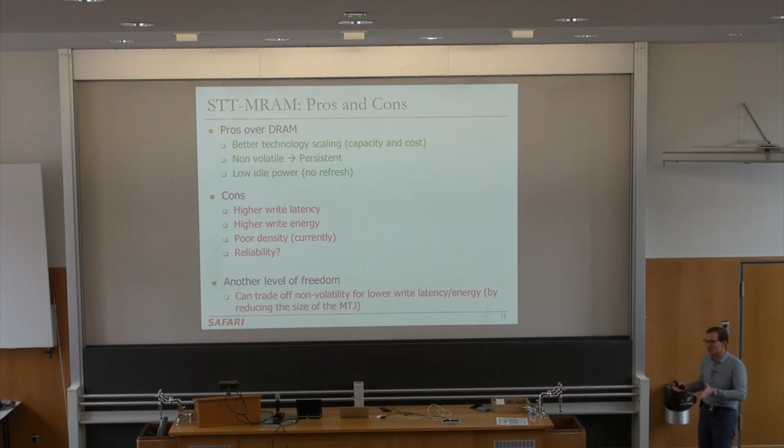Downsides also, of course, right? Persistence always also comes, if you have some data that's stored over there, now if someone else can read it as well, right? So there could be concerns in terms of information leakage. Whereas whenever you power off something, you erase the data, or you think you erase the data. And as a result, you may have less leakage. So those are issues that I don't go into over here, of course, because that depends on the usage model of the technology itself. So this is the main reason why it's difficult, I believe, to replace DRAM with STT-MRAM today, poor density. But this is a memory technology. You could use it even in the register files, right, if you really want to. But let's not go into that right now.